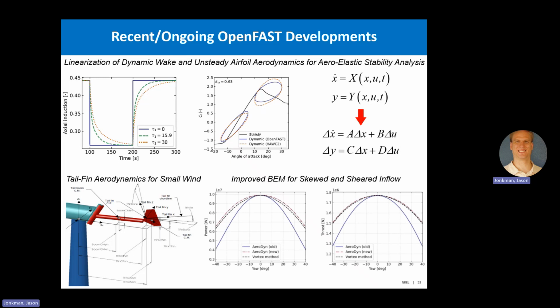Emmanuel, a really nice presentation on this one this week, showing our BEM improvements for 2 things. One is high skew. So if you have a high yaw error or a high tilt or something of the turbine, this is showing the comparisons of BEM old versus new relative to OLAF, where we trust it definitely more. And basically the old code, things like power were like a cubic loss, a cosine cube function. And I think in reality, it's cosine squared or close to that. And the new BEM definitely shows that, which is great. So high yaw, much improved in this version.